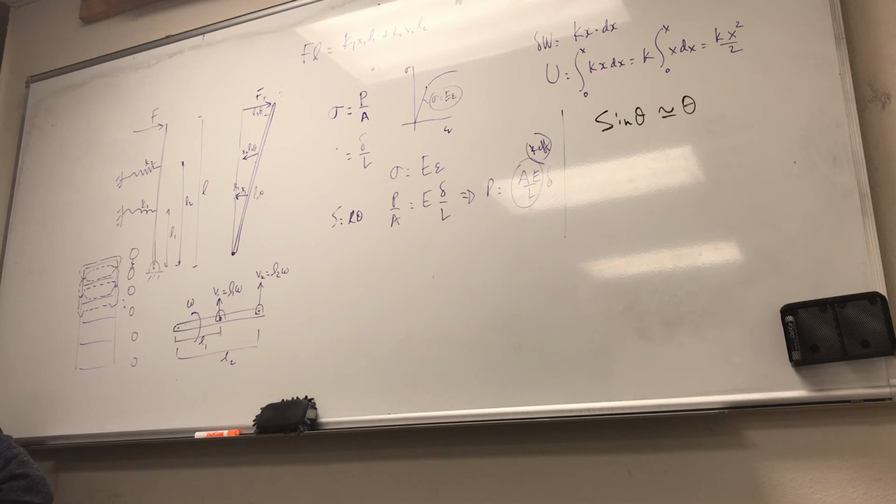Do I want to combine all the masses to coincide with this point, with this point, with this point, or somewhere else? Okay? In this case, we're choosing that the equivalent mass will be combined so that it is just here at this point. So x equivalent is going to be x1, right? So when you rewrite this equation, you find that m equivalent is equal to m1 plus m2 (L2 over L1) squared, and so on. That's all arbitrary, you just have to change how you do your moments. Yeah. So there you go.